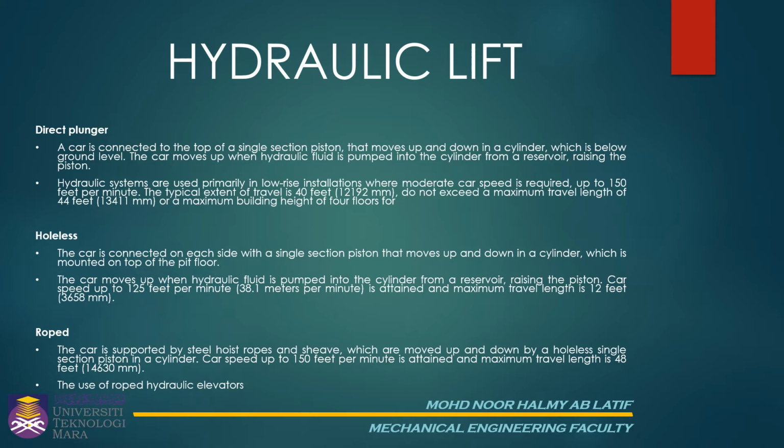Hydraulic systems are used primarily in low-rise installations where moderate car speed is required, up to 150 feet per minute. The typical extent of travel is 40 feet. Do not exceed a maximum travel length of 44 feet or a maximum building height of 4 floors.